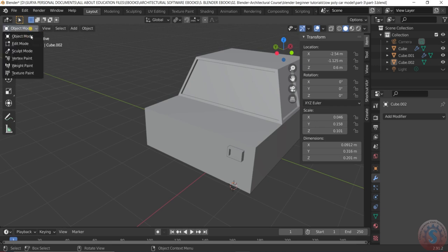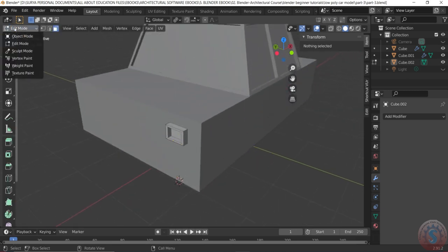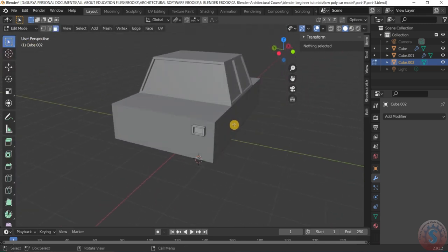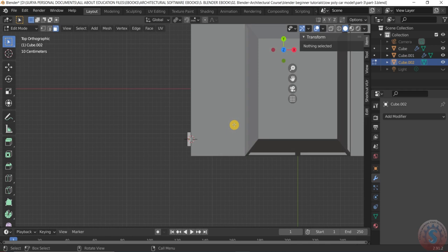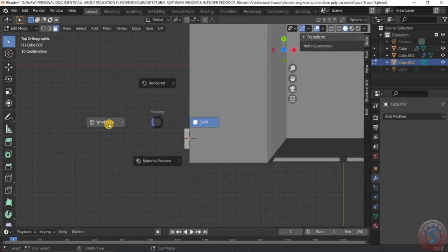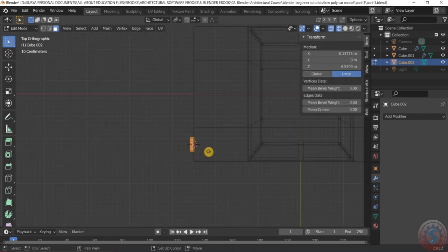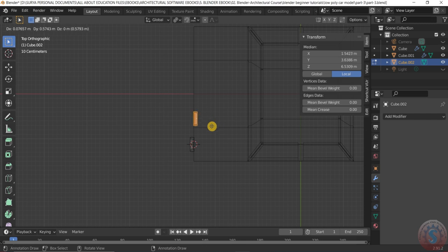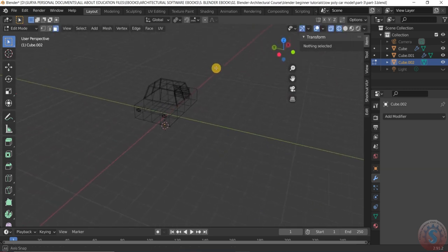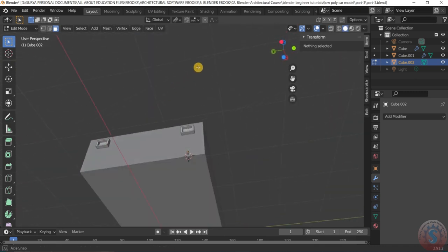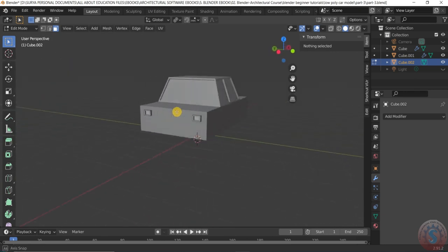Then after, I'm going to the edit mode. You can see on the object mode it is selected, and go into the edit mode and go into the Z and the wireframe and select the object by using the shift D to duplicate this, and go into the Y direction here. By using the control key you can adjust the same size on bottom and Z. Go into the solid. See the two lights are created. You can also create it by using the mirror, it is possible.